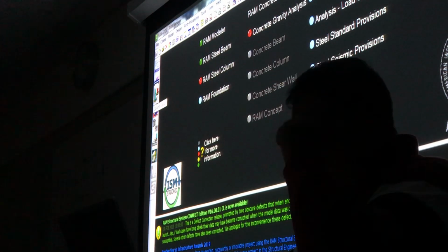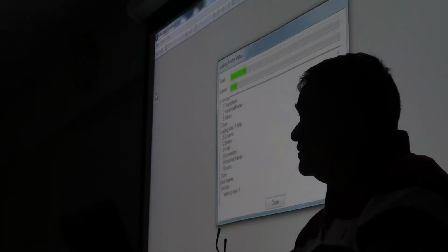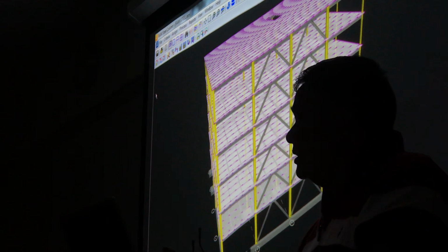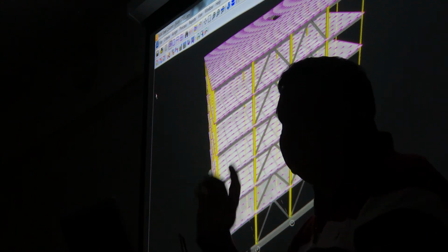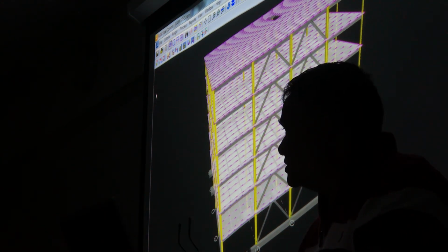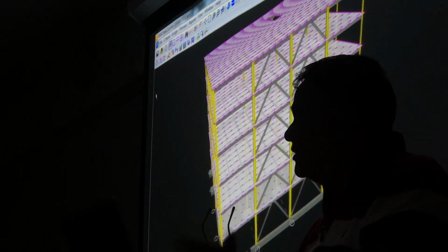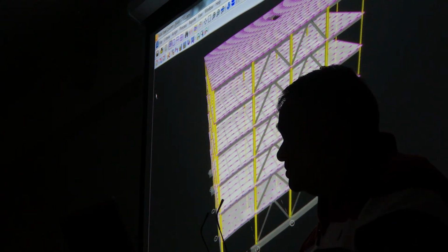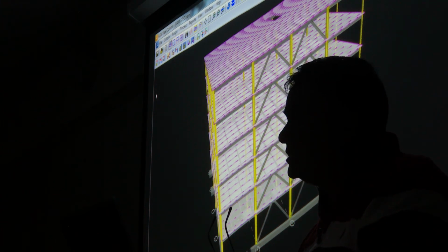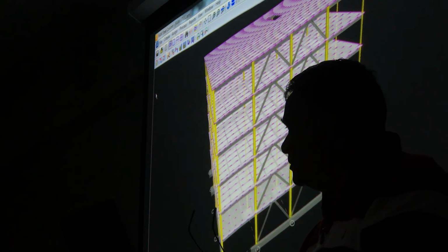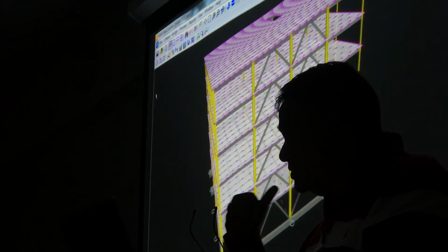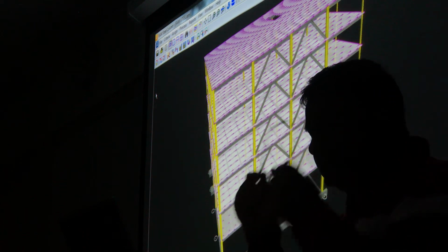Let's go into the column designs first. Now, again, there is a difference between this one and concrete. In concrete, we cannot do that because the same column takes moment also. The same beam takes moment because the concrete connections are rigid connections. Even though we are saying those are gravity columns, that column takes moment. Here, for a steel structure, it's much easier because the gravity beams don't take any lateral loading. In concrete, you cannot just say that because those columns will be taking lateral loadings.